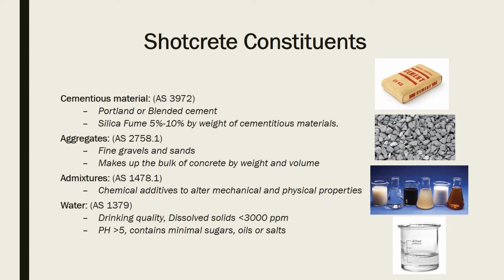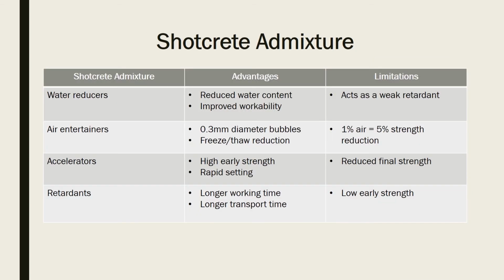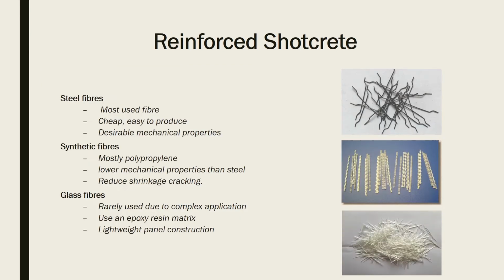Admixtures include water reducers to create a fluid concrete without adding more water, air entraining agents to produce minute bubbles within the shotcrete, accelerators to speed up the hydration reaction, and retardants to slow down the hydration reaction.